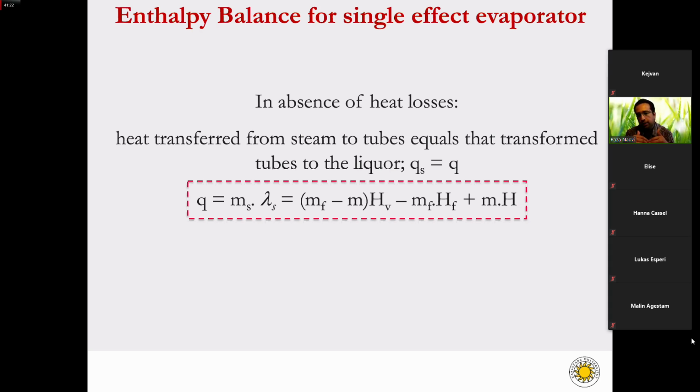Now, the opposite: when the vapors give out their energy, they become liquid. They transfer from the gas phase or vapor phase back to the liquid phase, and the temperature does not change, it will remain the same, but they give out their energy, and that is called latent heat of condensation.